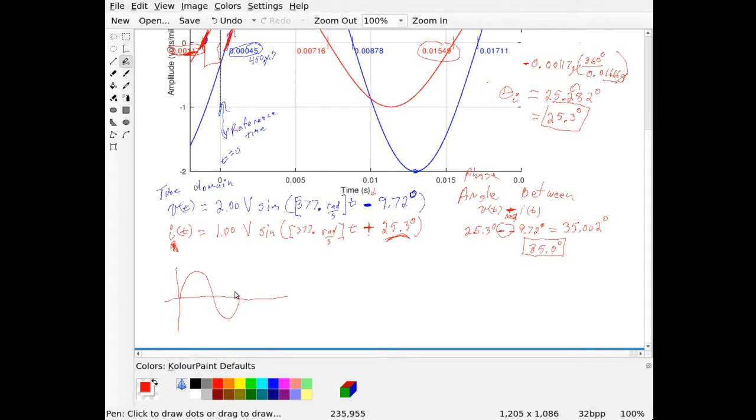When we look at this sine wave, you see that it's got a positive value and a negative value. It's positive for half the time and negative for half the time. So if we looked at the average of this waveform, v(t), the average is equal to 0. So the average voltage is equal to 0 volts.